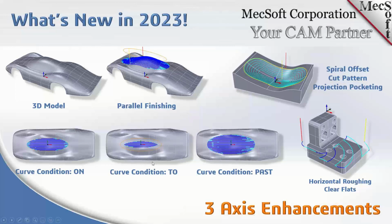So you can just draw the curve that you want to machine, and these are the different on, to, and past conditions lined up here on the bottom. And then up here in the top right, there is the offset cut pattern in projection pocketing. And also on the far right, this is just a picture of the robustness of the horizontal roughing clearing flats option. Oh, it also applies to multiple levels, but also in the clear flats.